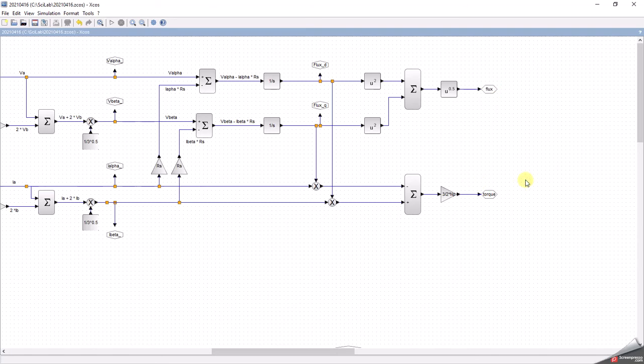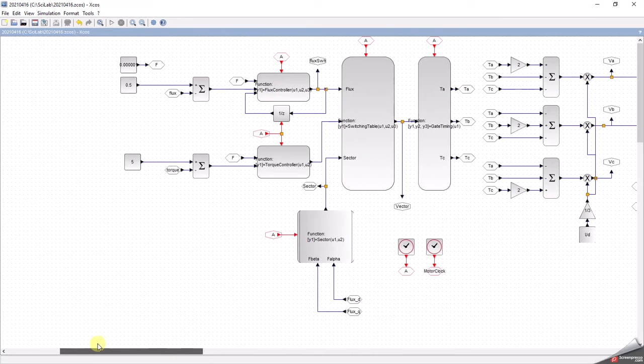And once you've got those two elements, torque and flux, then you can start comparing them against set points. So those are two DC-like terms there. This over here. Now, we have a controller, which is essentially a hysteresis controller or a bang-bang controller.